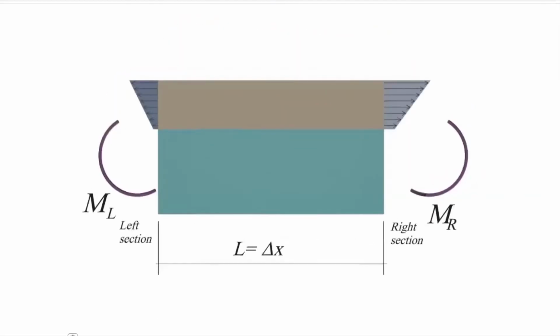So looking at that from the side, we can see the bending stress is going to be non-uniform on this section. It is actually 0 at the centroid, and it is linearly increasing when we get away from the centroid. The bending stress on the right and on the left are not equal to each other because the bending moment is different. So MC over I, when M is different, the bending stress would be different as well. Now, on that block that we took out, we can determine how much would be the resultant force of those stress blocks on the right and on the left. I'm going to call them F sub R and F sub L.